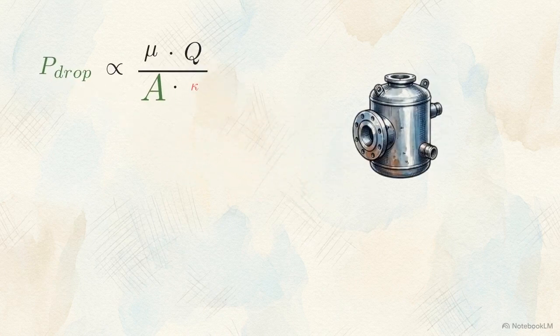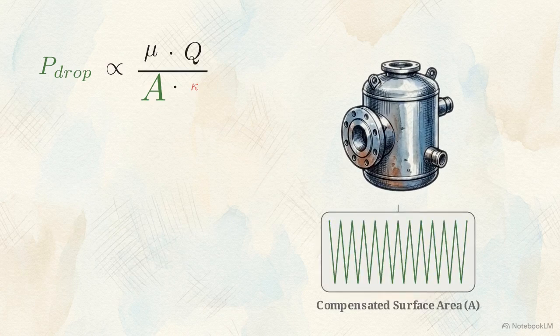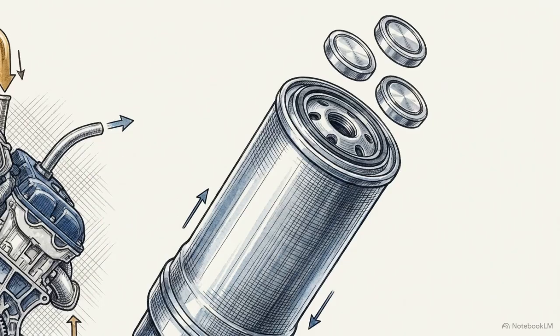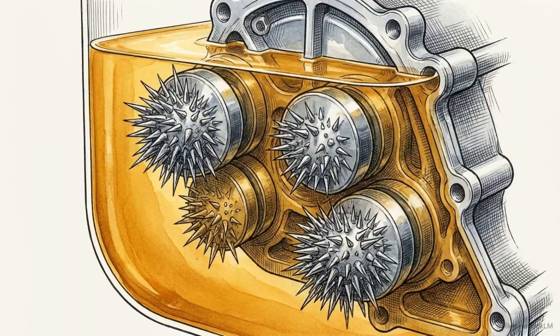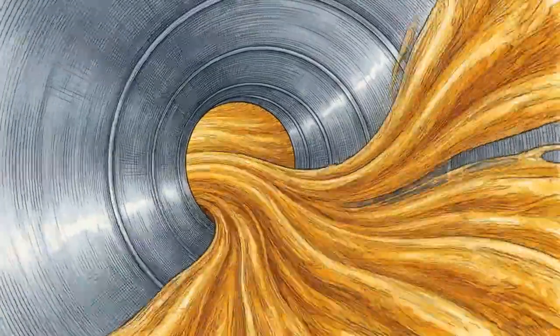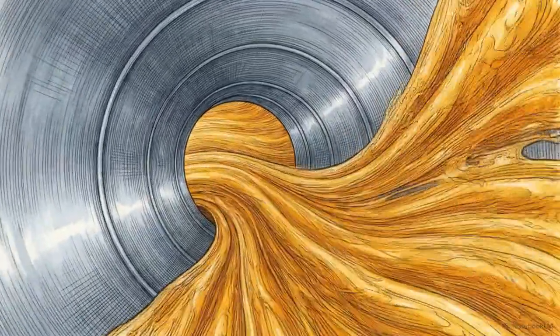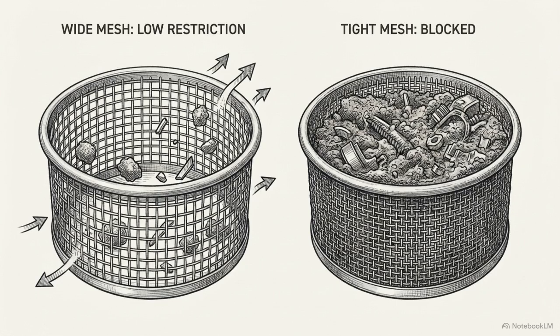We compensate by increasing surface area. An oversized canister with deep, sharp pleats maintains flow despite the restriction. We also position rare earth neodymium magnets at the inlet to capture ferrous wear particles before they reach the mesh, extending the surface life of the element. Manipulating these physical variables allows us to achieve microscopic filtration without triggering bypass valves or reducing oil volume. Because a 10-micron filter captures debris more efficiently, it loads faster than a standard element, necessitating more frequent maintenance.